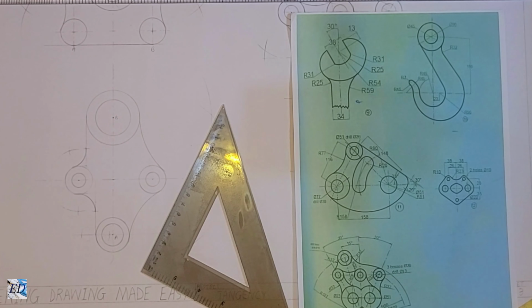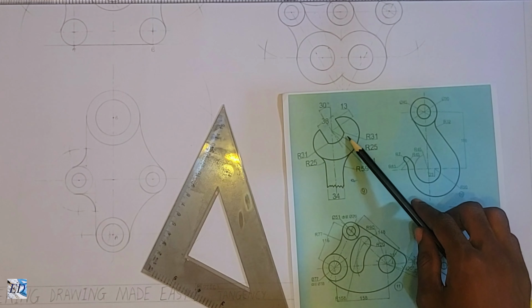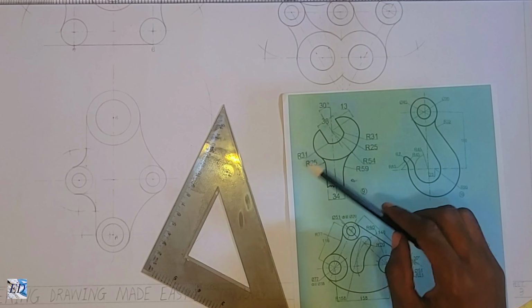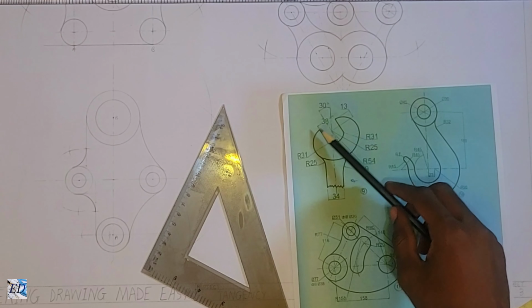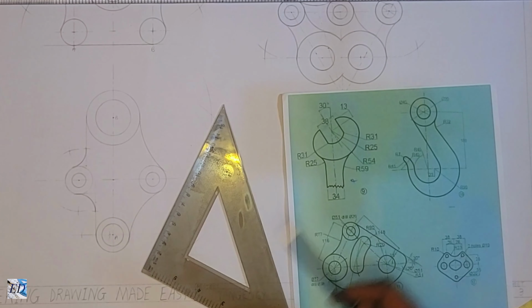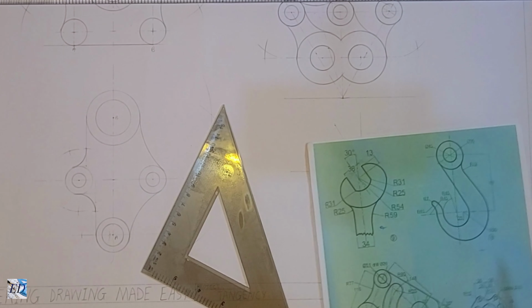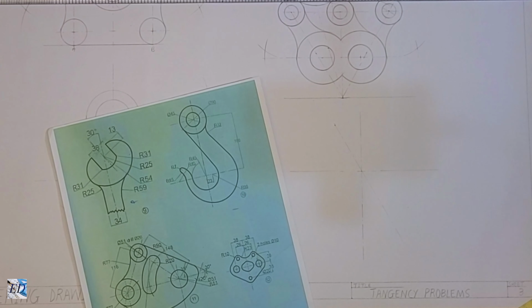Okay, so we are making some progress. You might not see it yet, but I'm making progress. The next thing we can do is draw these two parallel lines. If you take a look carefully, they are obviously parallel lines, and they are separated at a distance of 38 mm. So if this line just falls between it, you just divide the 38 by 2, and then that will be the distance from the midpoint to the other line on both sides.